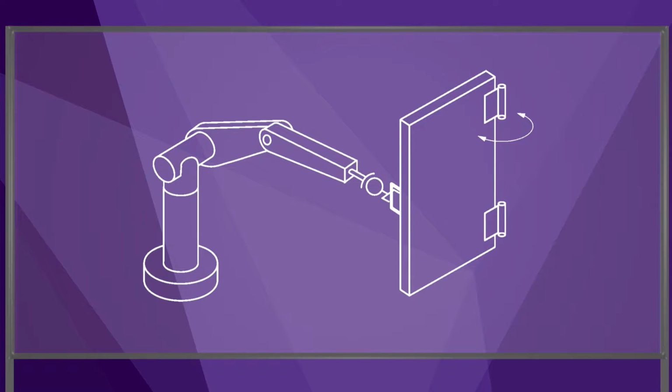When the gripper firmly holds the door handle, the gripper's motion is constrained to 1 degree of freedom, rotation about the hinges of the door. The robot can freely control the velocity of the end effector in this 1 degree of freedom. Simultaneously, the gripper can apply arbitrary wrenches in the 5-dimensional space of wrenches consisting of moments about all 3 axes of the door handle and linear forces upward or through the hinges. Essentially, the constraints provided by the door hinges partition the 6-dimensional space of end effector wrenches into a subspace of wrenches that cause motion of the door and a subspace of wrenches that push against the constraints.